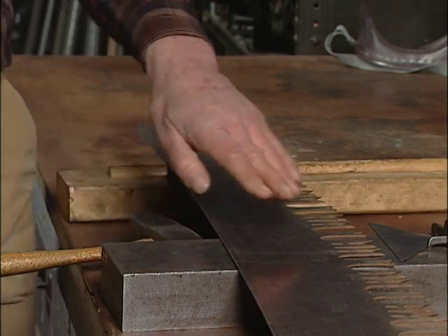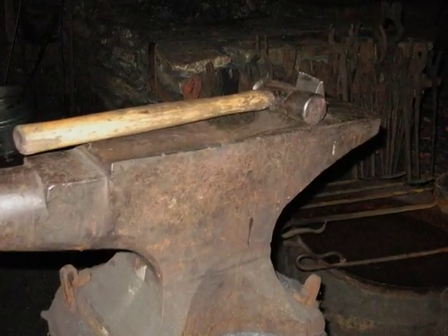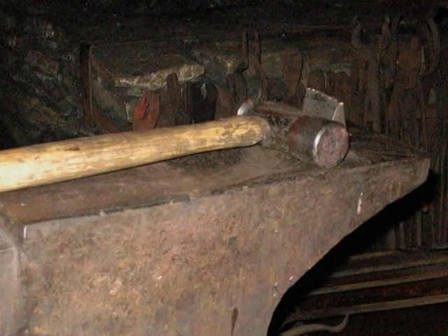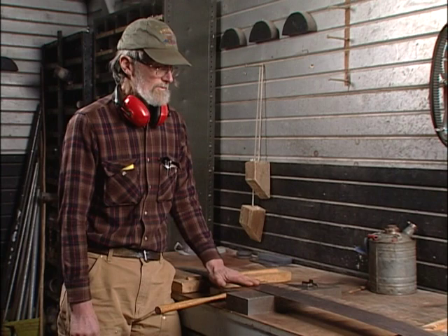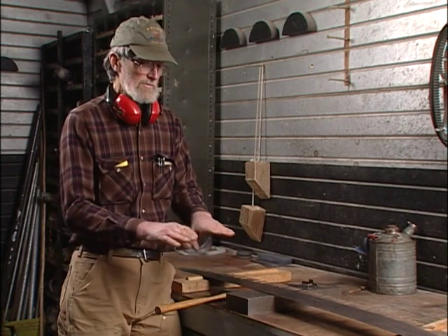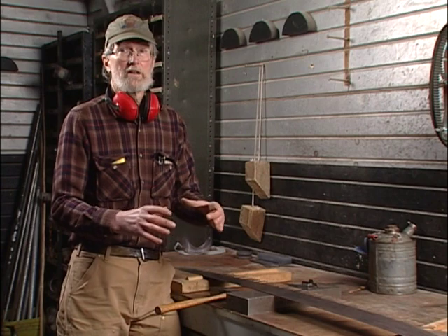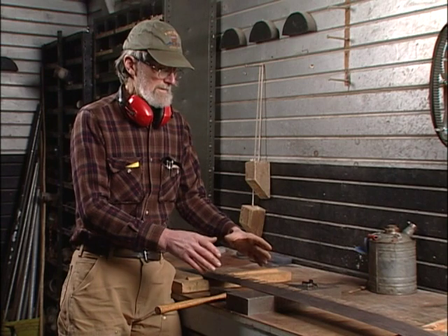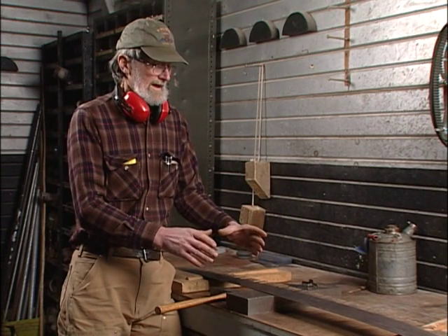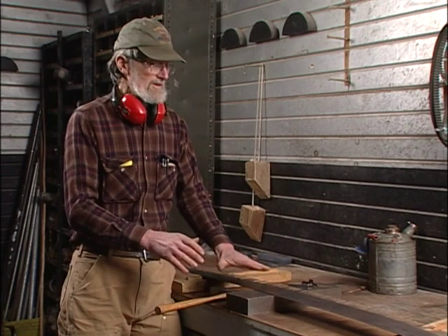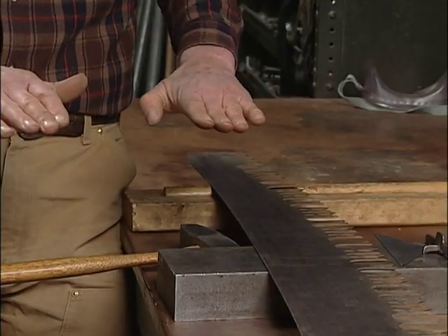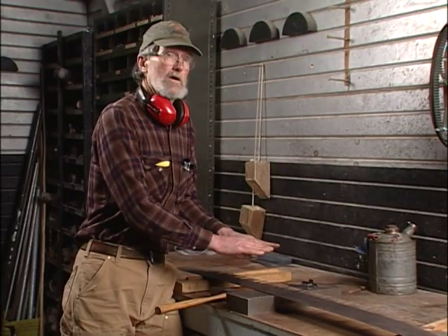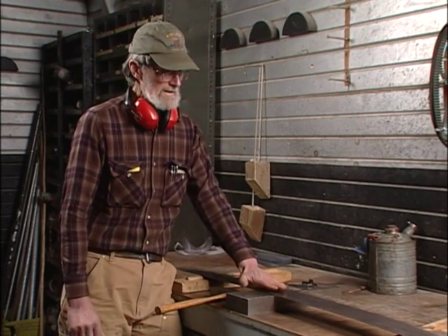For a number of years, I ended up using a standard shoeing anvil or blacksmith's anvil. And that worked pretty well for me. It has, of course, a hardened, chilled face on it, but in spite of that, I found that it would work pretty well. The one thing that you have to be really careful about using a blacksmith's anvil is that a lot of them have a pretty marred surface, just from the blacksmith work. And in order not to damage your saw, you need to make sure that you hammer on a part of the surface that's quite smooth. Either that, or you can take an angle grinder and grind the surface quite a bit smoother, so you have a smooth area to work on.